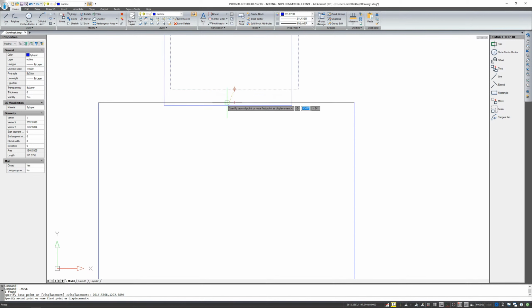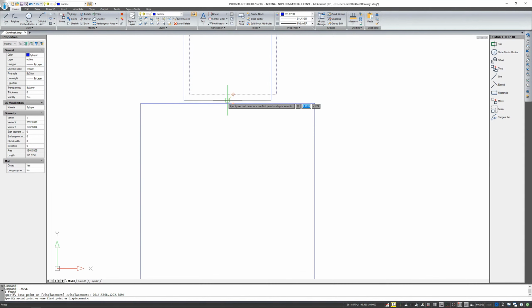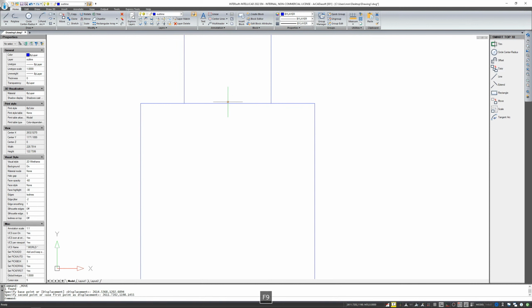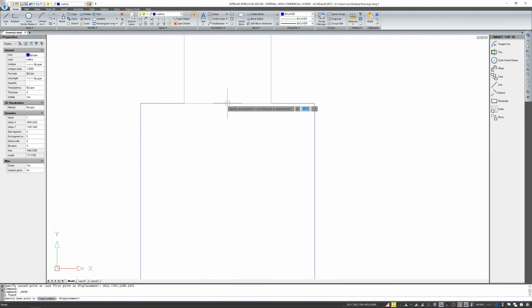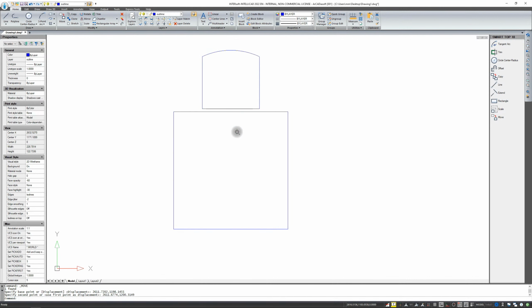And now I want these points to center, so I'm using this polar tracking. Have a look here. It sometimes doesn't work out as you want it to, and it doesn't quite catch, but you can go do it a little bit differently. Put them together and then center it and then move them apart again.